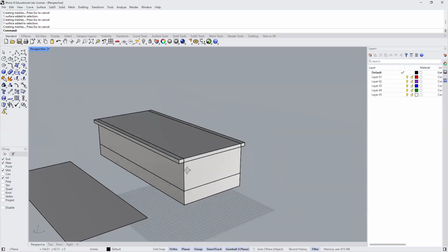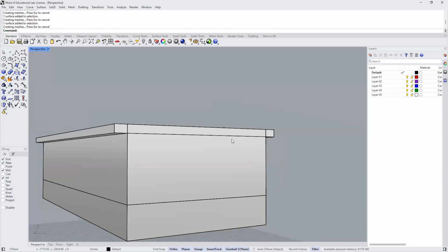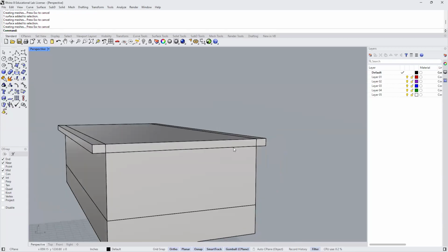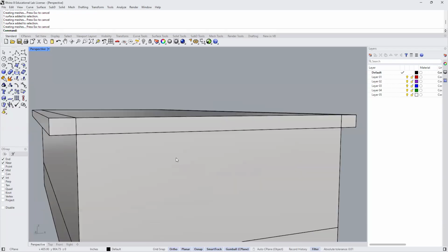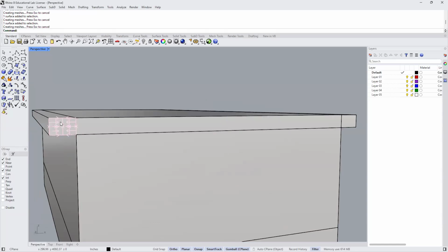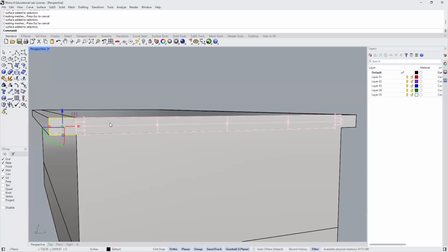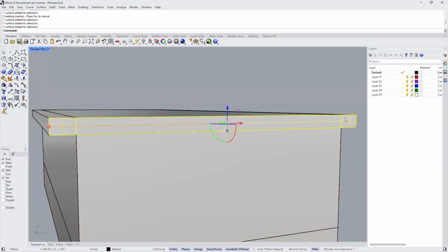And now what I would like to do is I'd like to extrude this surface here. But you'll notice what it's doing is that it's added 2 other surfaces. So I have to be real careful here. Zoom in right about there. Hold down Control Shift. Click on this surface. Still holding down Control Shift. Click on the other surface. Still holding down Control Shift, and then click on the final surface over here. So I give that a click. And now all 3 have been selected.